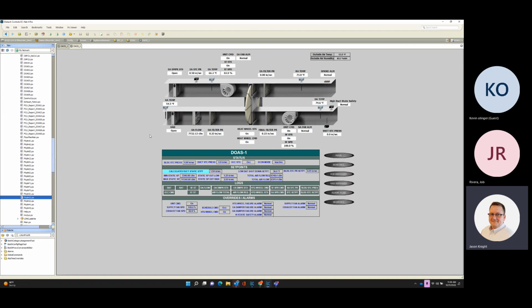It's just a very low speed that just keeps air circulating through the room. And a lot of the initial complaints that we got from the teachers are they're calling all the time, complaining, saying, my unit's not working, it's not running. And we look at the room and it's within set point, between heating and cooling set point. Room temperature's fine. The fan is at the minimum speed, which is 10%. And they can't hear it running, so they get all anxious, and then they put in these calls saying, my unit's not running, it's broke. I want somebody to fix it before it gets too hot in here. Well, it's just in ventilation mode, and they're ultra quiet.